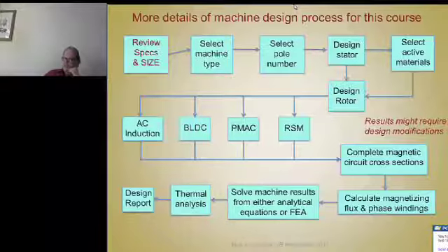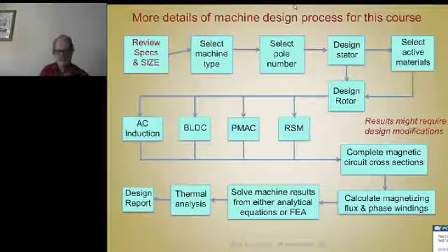For example, if magnet prices continue to escalate in cost, maybe you want to use your automated motor for a car or a traction application as an induction machine for a few years, or a reluctance synchronous machine until the price of magnets comes back down, and then maybe you want to put the permanent magnet rotor inside that stator. Or maybe you want to offer both at two different prices and two different performance levels. That's another thing that might be worth doing.